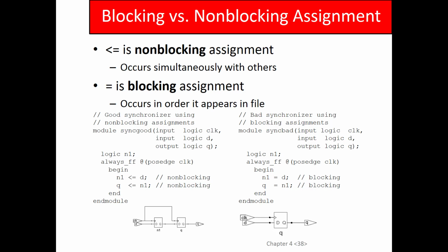No, well, in this case, this statement would basically update N1 and Q at the same time, right? They would both get D, right? So it all happens instantly. Yeah, so blocking means assignment statements take effect right away, is one way to remember it.